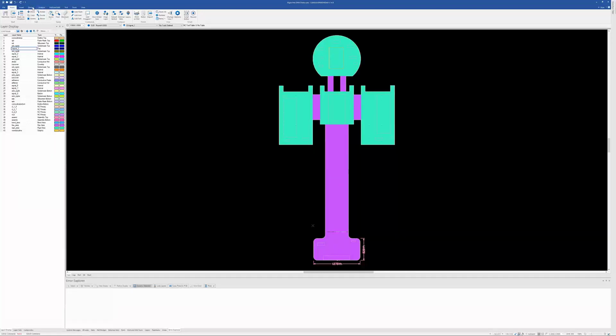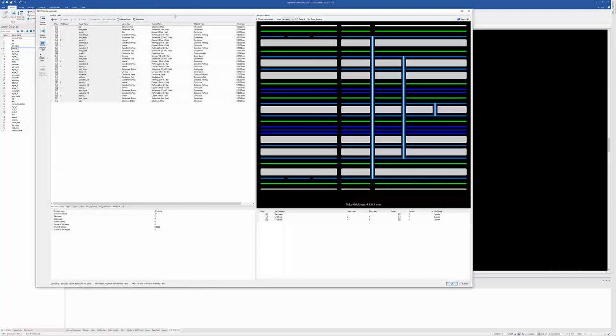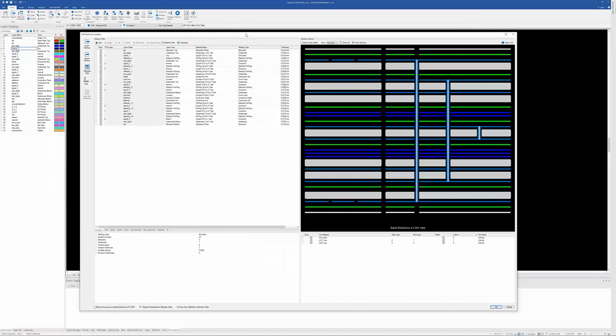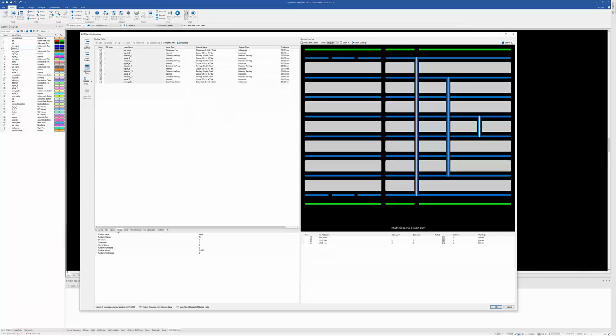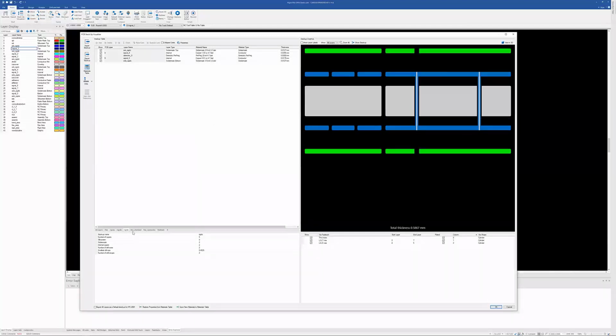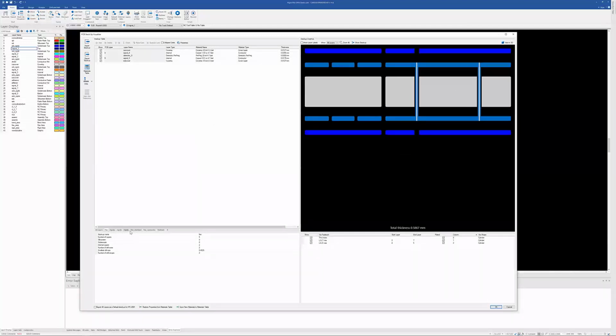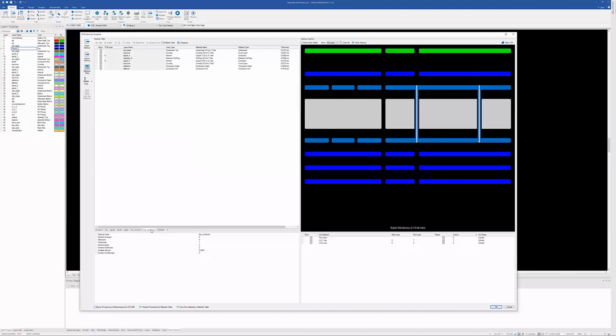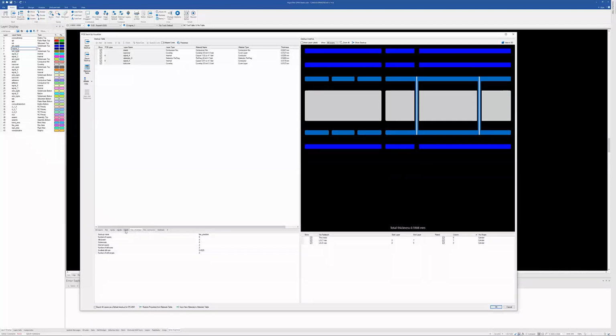And in doing that, we added concepts to the stack-up visualizer, so no longer do you have just one generic stack-up. You might have one for a rigid area, various rigid areas, various flex areas, and all of those, of course, can be modified. You can change the dielectrics and so forth, and you can even import and export those.